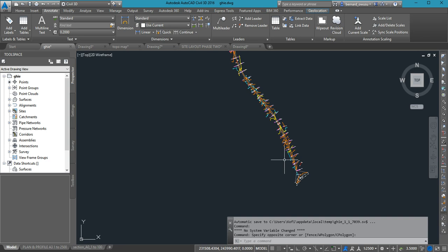So as I said, before you do your horizontal alignment design, we are doing a simple single carriageway, and we are saying that the width of the carriageway is 7.3. We have shoulder 2.5, drain 1 meter, and that is it. So at worst, the minimum total width that we should have should be about 14.3. Good, so please take note of that. But that is one option. You can decide to use a different width, you can use 3.5, whatever you want to.